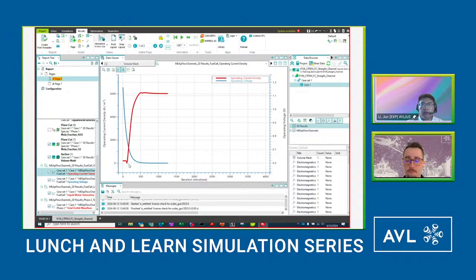The operating current density versus the voltage changes over this simulation process from the beginning, the open circuit voltage, to 0.6 volt. That's what we achieved in a little more than 1200 iterations. Once the user has this case and reruns other cases, they can save this post processing as a template, then just load in the template and apply it to a different case.